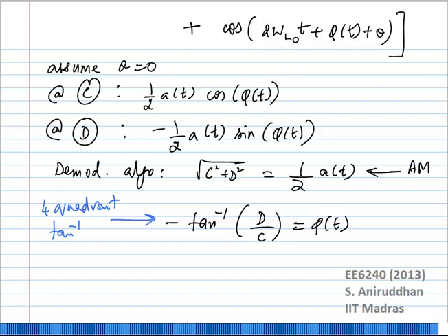No. This is extraction in the digital domain, but I am just showing you an example of how you would extract it. You would probably have an ADC, digitize it, and then you can do exactly this in the digital domain. So at the end of the day, whether it's digital or analog, we want to extract the amplitude and the phase. We would never or almost never extract any information in the analog domain. Okay, especially because the modulation is in a digital form. There is no use demodulating the analog component. Okay. So now it's very easy to see how you would demodulate it.